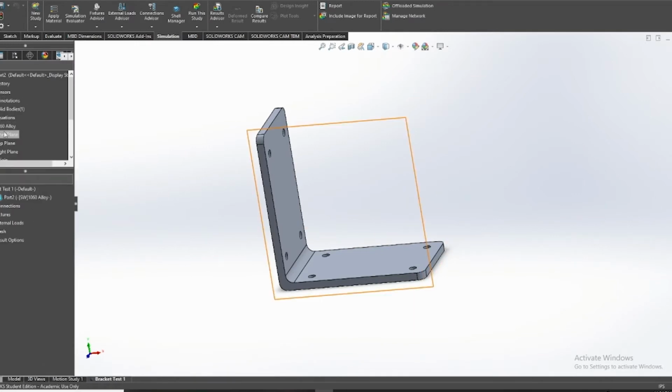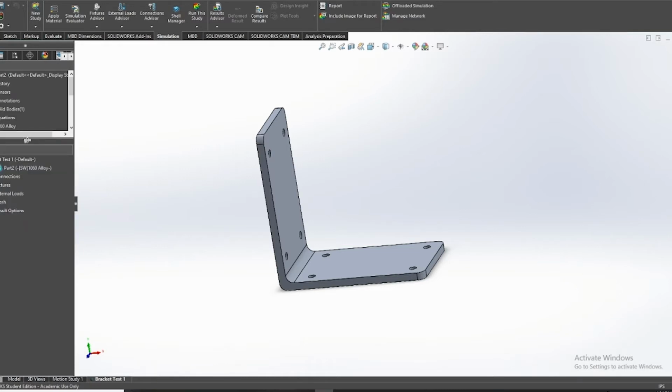You'll notice I already have my material defined up in my part, and it's always good to define your materials. I'm not great about it, but I'm trying to get better. Always define your materials when you get the chance. It helps with determining the weight of the bot, whether or not a motor can handle turning around your shooter or picking up your intake. Really, really helpful stuff.